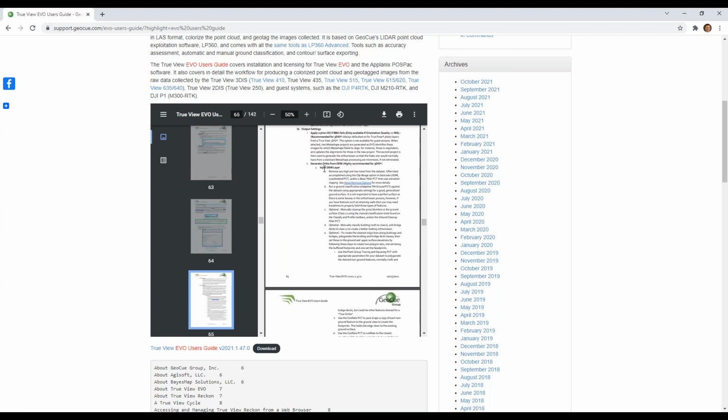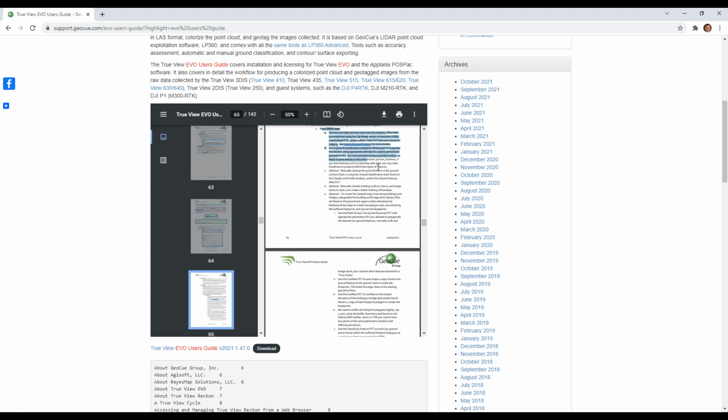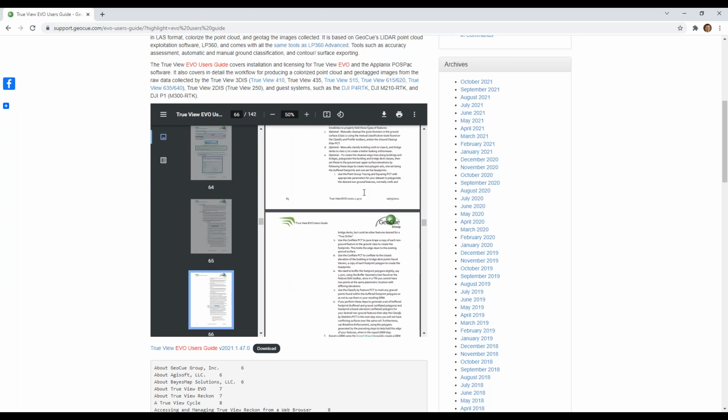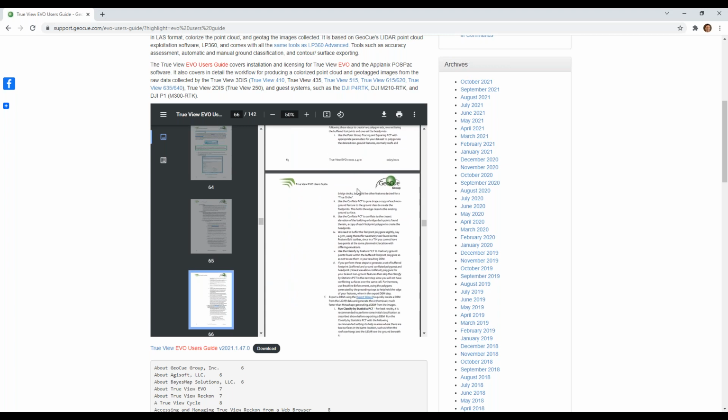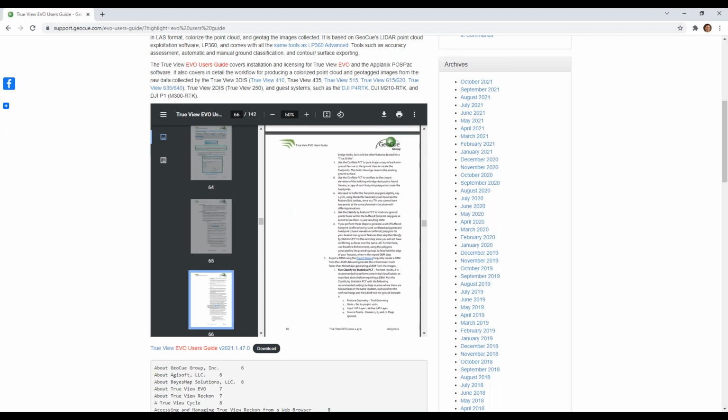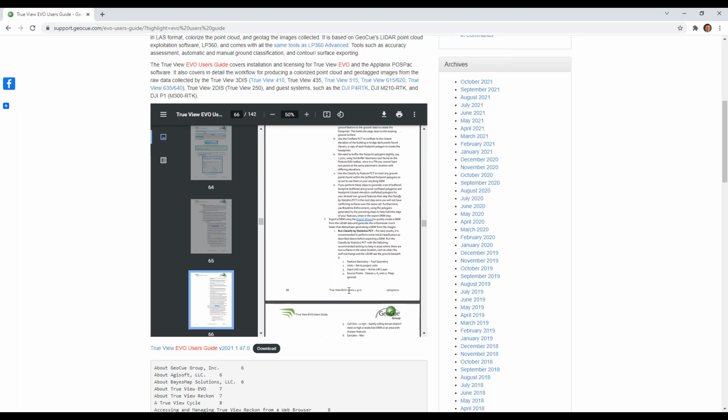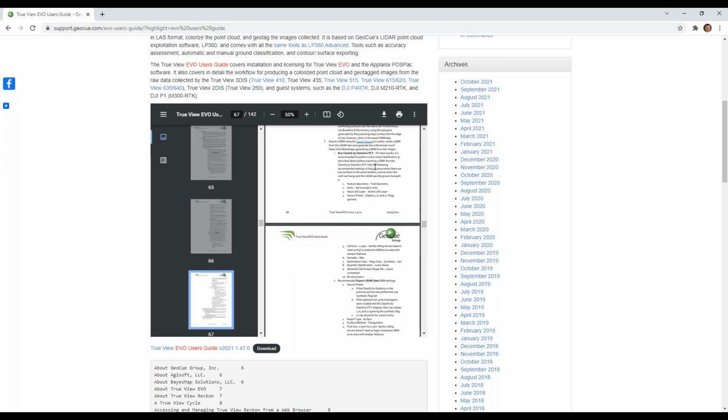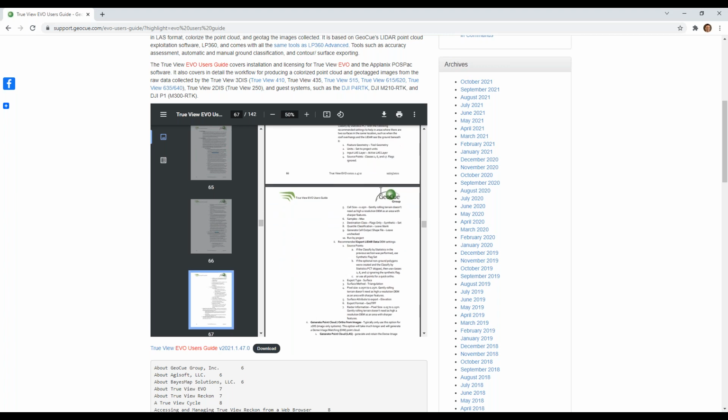There is a write-up in here that talks about the digital elevation model and the different recommendations from doing a very quick elevation model to actually doing a little bit of classification, doing some manual classification, maybe doing some above ground features or bridge deck classification if you have those, or even going so far as creating some break line elements to even make that better. And it includes a section on some recommendations for how to run the statistics point cloud task in order to get a better elevation model out of those. I try to give that as a step-by-step process.